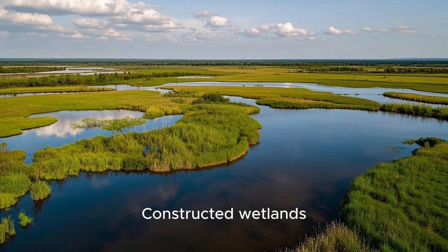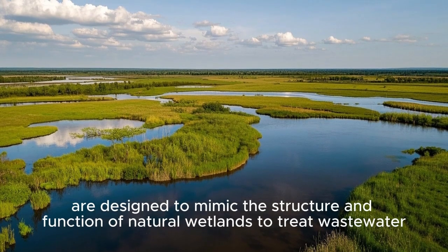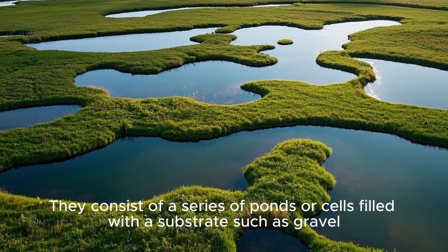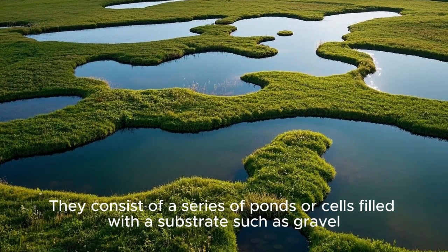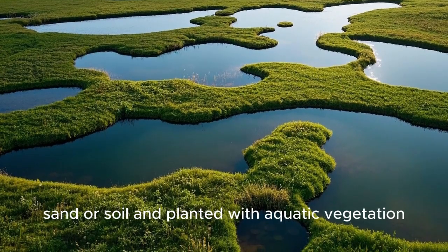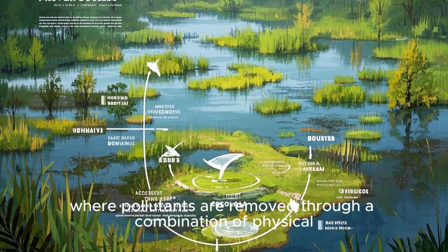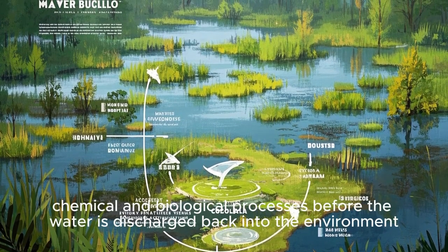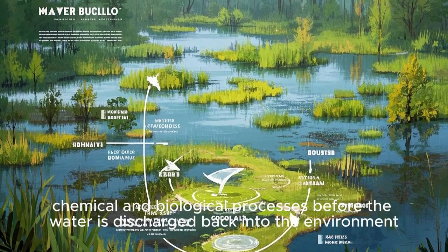Constructed wetlands, also known as artificial wetlands, are designed to mimic the structure and function of natural wetlands to treat wastewater. They consist of a series of ponds or cells filled with a substrate such as gravel, sand, or soil, and planted with aquatic vegetation. The wastewater is passed through these ponds where pollutants are removed through a combination of physical, chemical, and biological processes before the water is discharged back into the environment.